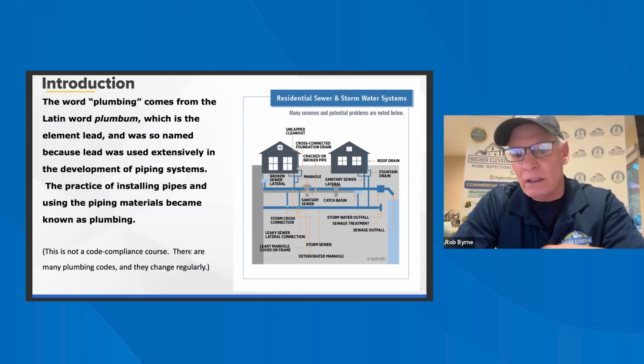And again, most water heaters have this statement on it. Discharge pipe, we just talked about that, part of the inspection. You're going to look for that and make sure it's there. Make sure there's no threads on the bottom of this pipe over here, because then when it leaks, sometimes people just screw something on it to keep it from leaking, and you defeat the purpose of it. Very, very important on that aspect of it.